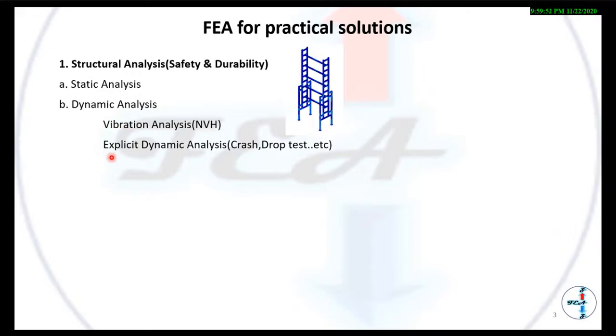And coming to explicit dynamic analysis, here we are dealing with structural interaction between two different structures. It is crash test, drop test, and metal cutting, metal forming. So this load case will fall under explicit dynamic analysis. The next one is thermal analysis.